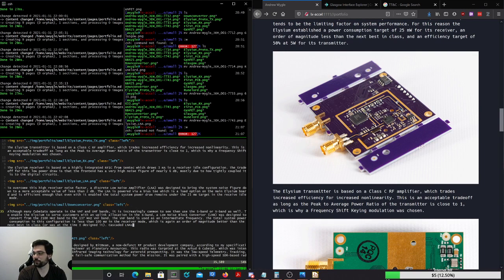Anything else? No, I don't think so. Do you get more watts per meter squared from a solar cell on orbit than at the Earth's surface? Yes, you do. So there's, is it AM? Is it the atmosphere model for how much illumination a solar panel gets? AM1 is basically Earth's surface, and then AM0 is space. So you do get more watts per meter squared. It's not a ton more because the atmosphere is relatively transparent at solar cell wavelengths, but you do get more.